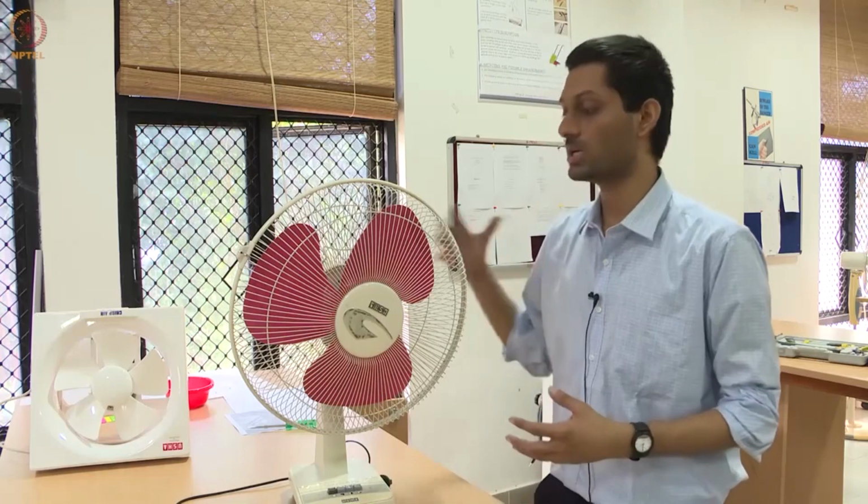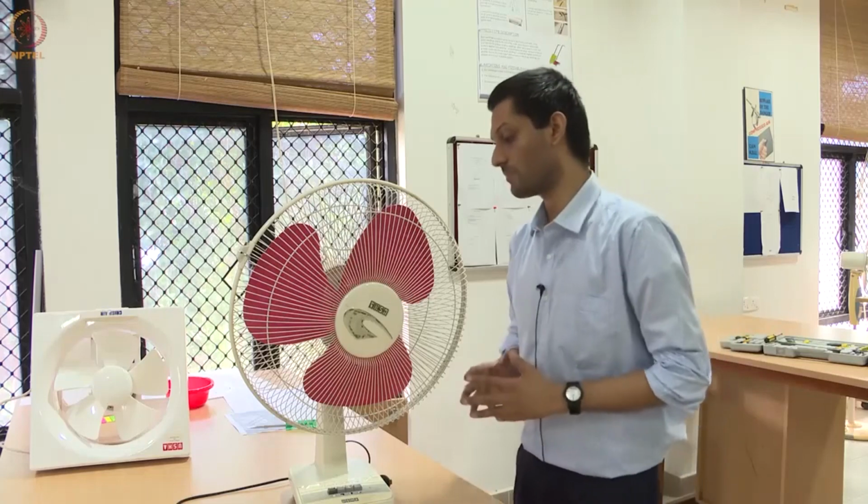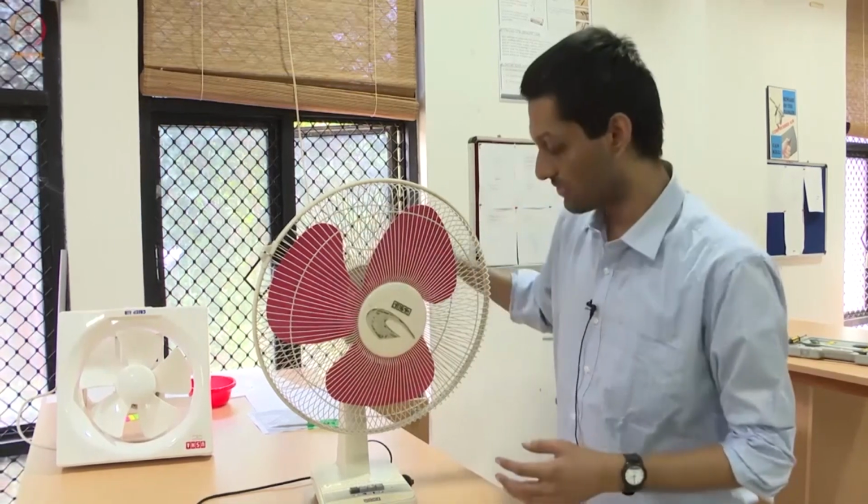So I urge you to please read about capacitor start and run motors, and also read about motors wherein the starting winding is disengaged by the use of a centrifugal switch. These kinds of motors, where the starting winding is disconnected, are used in pumps and certain other industrial applications. In most consumer grade appliances, the motor is typically a capacitor start and run motor. So that is about the motor. It's a single phase motor.